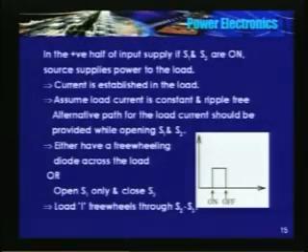Say the supply voltage is 50 hertz. Here is a signal generator which generates 50 hertz. I will take the sine wave and compare it, and these are the switching instants. But then what is the relationship between this sine wave generated by the signal generator and the supply frequency? In other words, they have to be synchronized. If you synchronize them, it's fine. So, how to distribute?